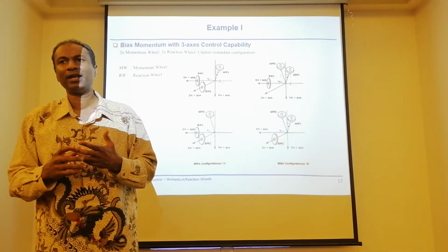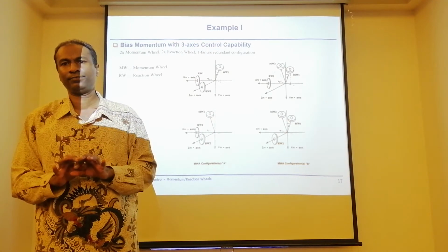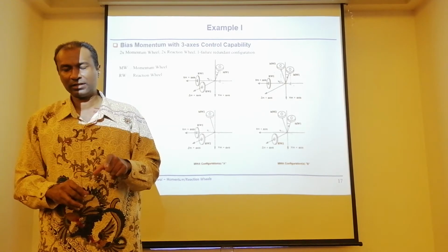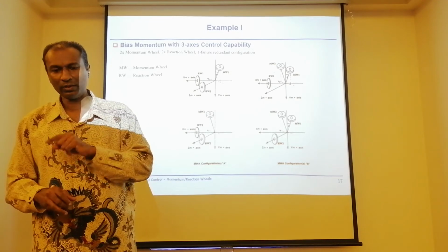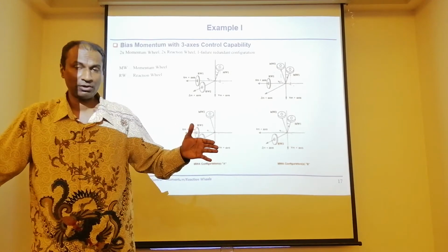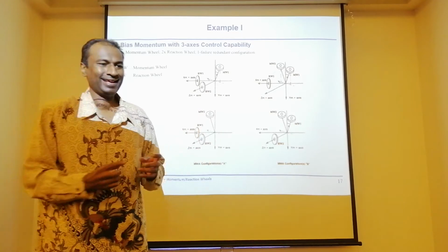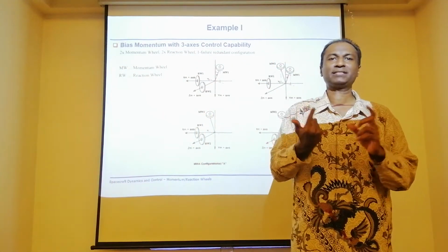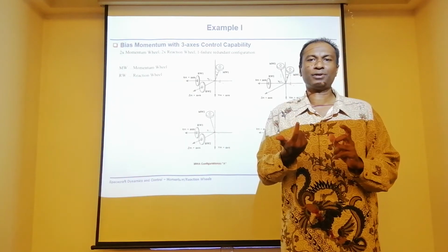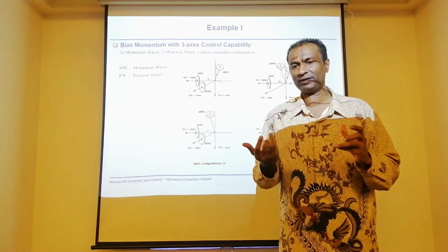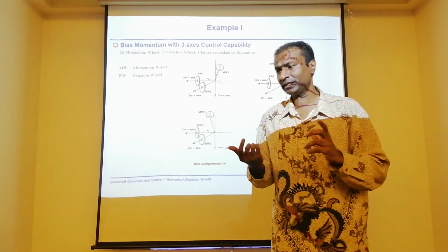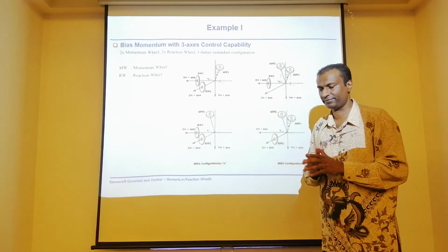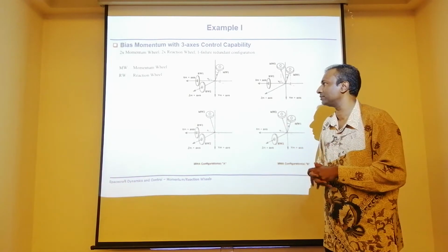So normally we have a redundant wheel. Redundant wheel is mandatory because when there is a wheel failure for a very long mission, 10 years mission, at least 1 wheel is there basically like a spare tire in the car. Okay, but of course now you do run flat. But we have that in order for us to have a safety margin of operation.